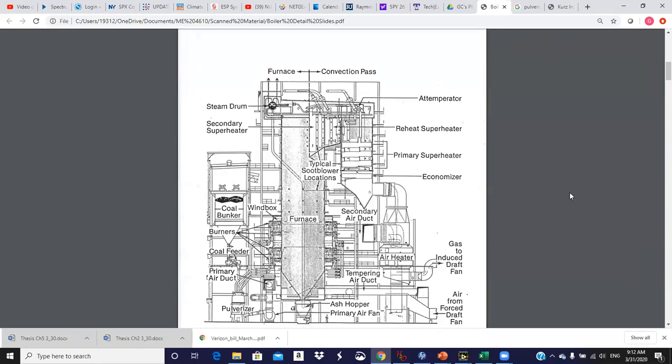That's what is feeding the air to the pulverizer, the hot air, and then there could also be a cold air, so there's going to be some blending. You don't want it too hot or you increase the fire potential. But that hot air transporting those coal particles tends to dry them out. If they're wet at all, then it'll vaporize the water and at least take that into the boiler as water vapor instead of liquid water.